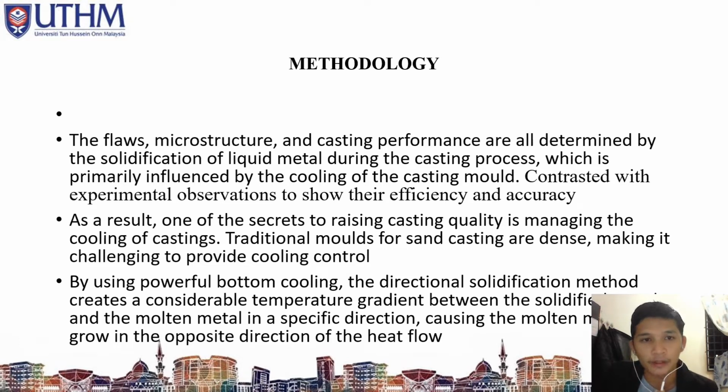First, the flows, microstructure, and casting performance are all determined by the solidification of liquid metal during the casting process, which is primarily influenced by the cooling of the casting mold, contrasted with experimental observation to show their efficiency and accuracy. As a result, one of the secrets to raising casting quality is managing the cooling of the casting. Traditional molds for sand casting are dense, making it challenging to provide cooling control.